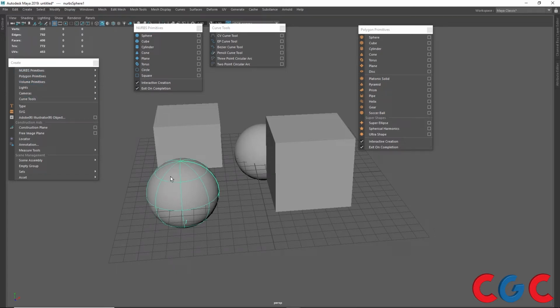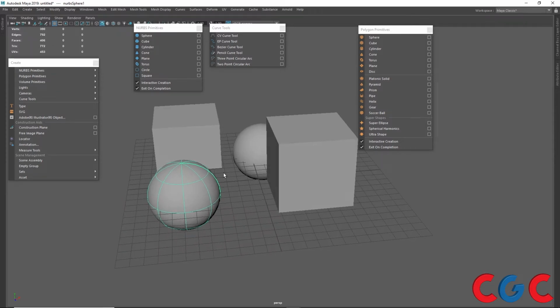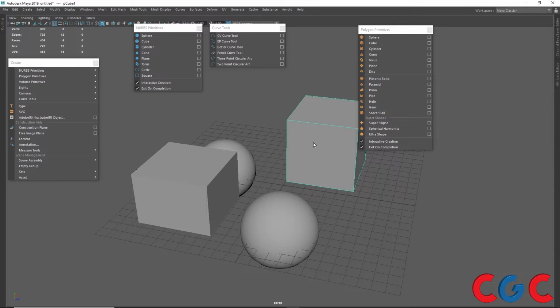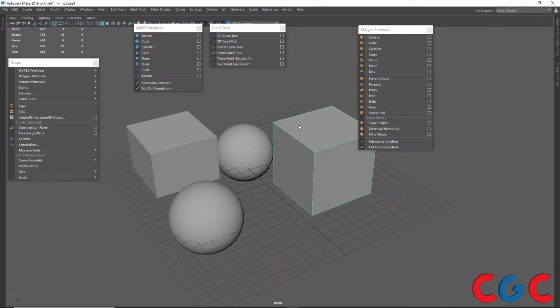But in this polycount we can see the difference. When I click the Nurb surface, I won't be able to see any verts, edges, faces or tris, but when I go and click polygon, I see numbers over here depending on the number of components it contains. Again, when I see this Nurbs cube, the faces are going to be separate, but in a polygonal cube, here we can see the components are intact.